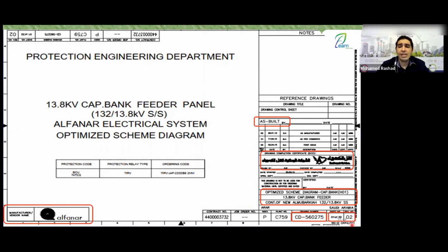And then here below, it tells you the number, meaning 1. So this is 32 sheets or 32 pages, and you have this as page number 1. Its revision number was something like 0, 0, 0, 1, 0, 2, 0, 3. This means the drawing has been revised and updated several times. You start making modifications, apply them, make modifications, apply them, and make modifications, apply them. So it shows you what is available to you. All right, so you can reach the latest revision and ensure it is the latest revision. Great, and once you see it, that's really good.